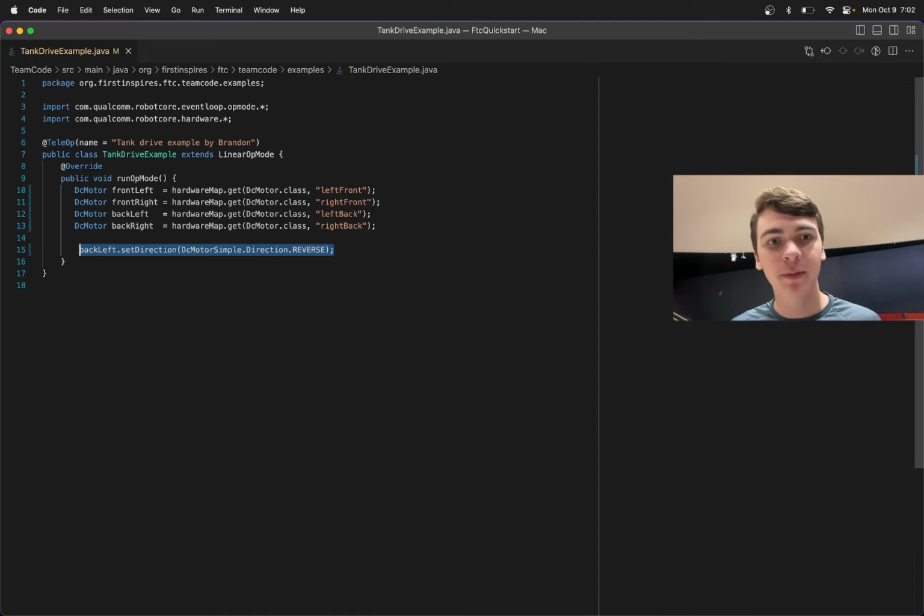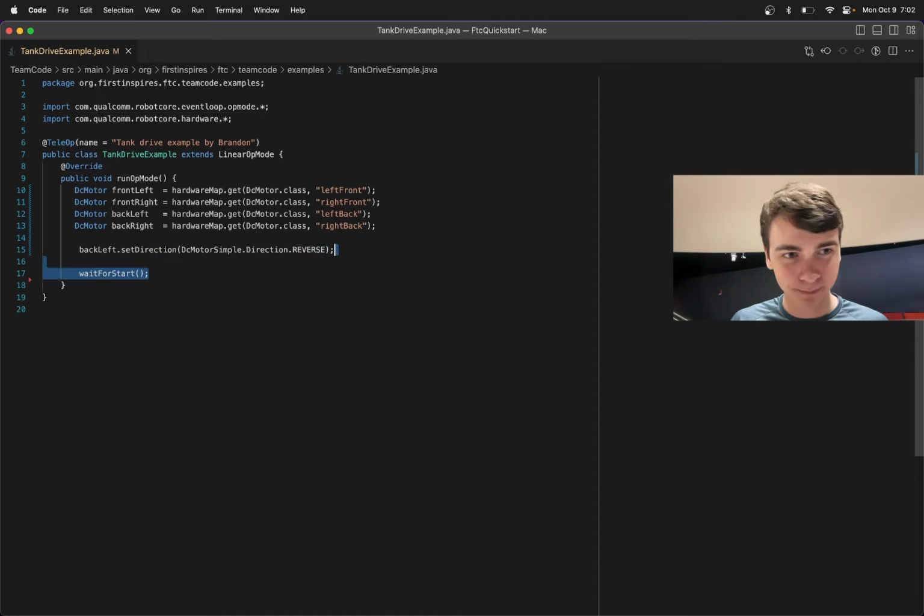And if you want all of them to be rotating in the same direction, you have to reverse two of them. Now, just by the way the chassis is set up for 750's Power Play robot, you only need to reverse one of them. That's why only one of them is reversed in this particular example, but that's something you'll have to figure out. We'll talk about processes for figuring out which motors need to be reversed in future videos.